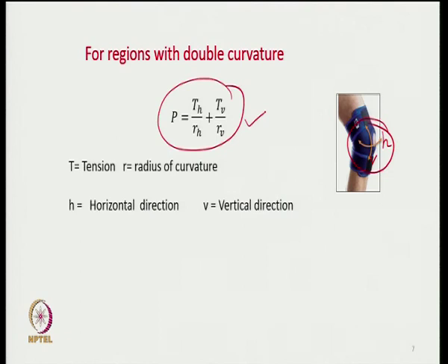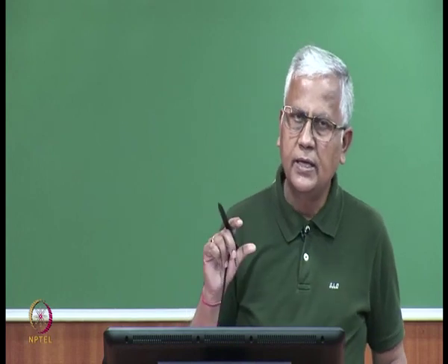So, this will be required in some cases, or if we want to be very accurate, then we have to use these equations, and we need to therefore know what is going to be the stretch in the fabric in both the directions. If we know the stretch, then we can find out how much tension is developing in that stretched fabric, which will depend upon the property of the fabric.